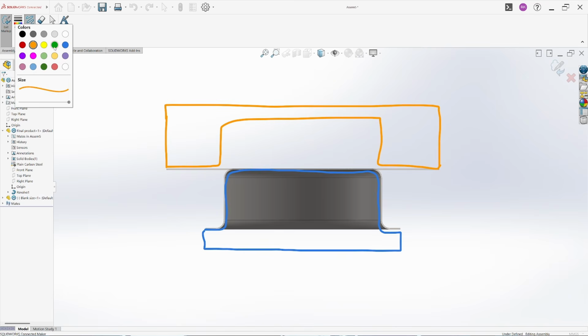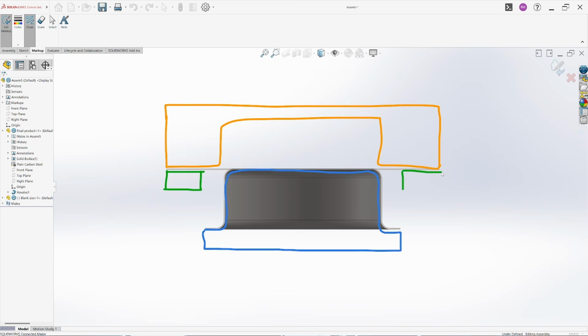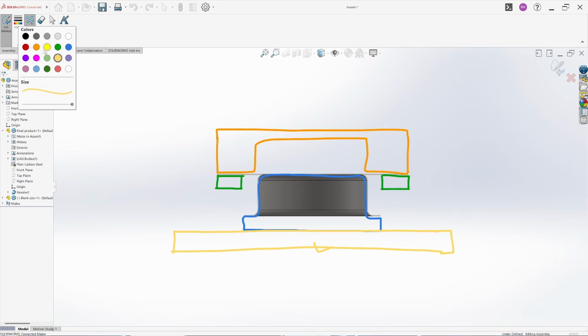Now we will have our blank holder. So the blank holder will be somewhere here, which will support our flat blank. And we will mount our punch over the base plate. So let me also draw the base plate. So the base plate will be somewhere here. Okay, and we will mount our punch over the base plate. So this is our base plate. Okay, and we will support our blank holder using the gas springs, right? Something like this.